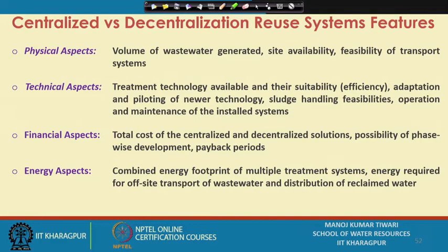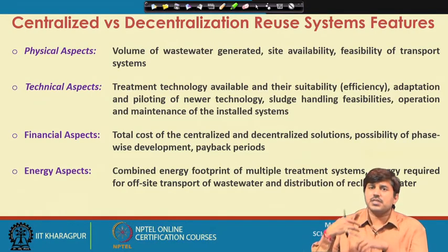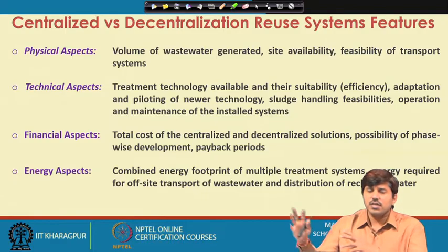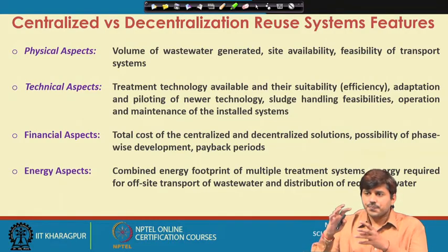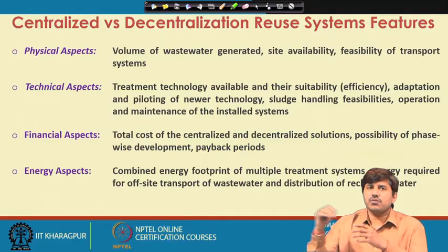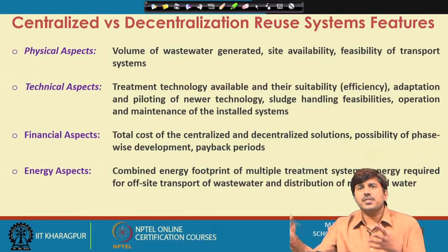However, if we go for some intermediate scale, we may see that it is more economic than a centralized system, because it is not just the cost of the treatment plant; it is the cost of transportation, which is very high in a centralized system and almost negligible in a decentralized system. If you have to transport that water, you have to lay a pipe network, put in pumping stations and manholes, and arrange the entire sewer network throughout the city, carrying those big sewer pipes.